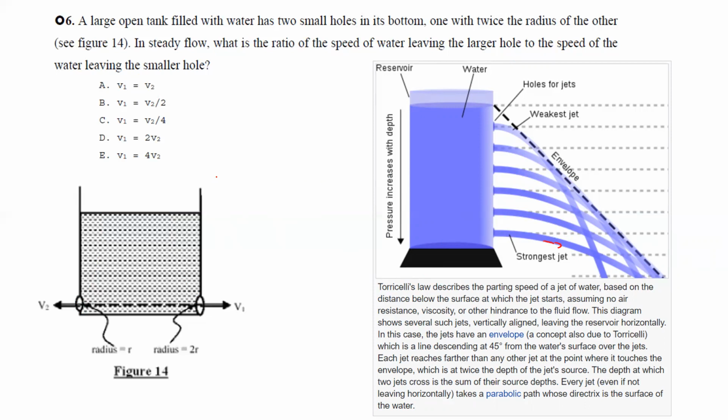So the speed of the water getting out at a certain height is just square root of 2gh. That means here, for instance, if I put this upward, when the water gets out, it will get out with the speed of square root of 2gh, and it will go up, up, up, up to the same height, and then fall down again. Okay, good. So here, the speed is independent of the cross-sectional area of the holes.